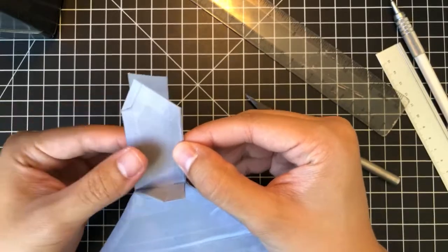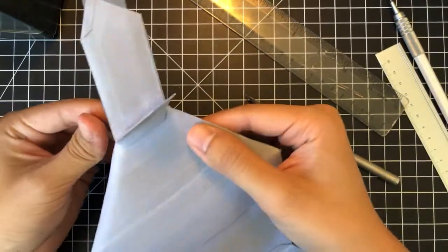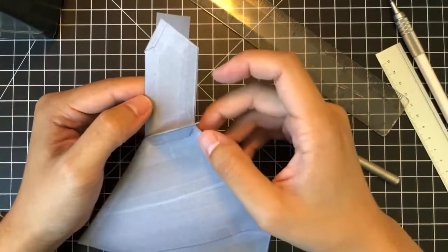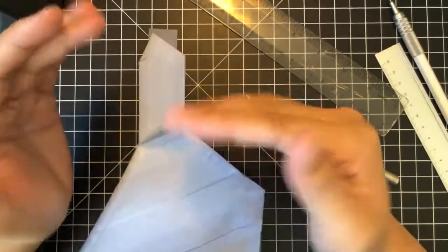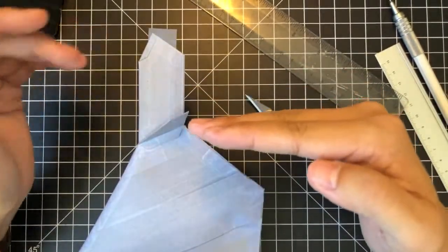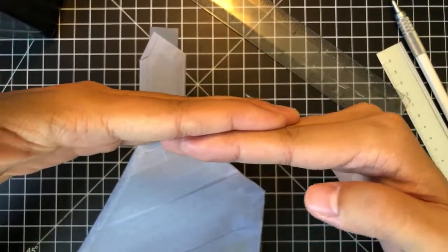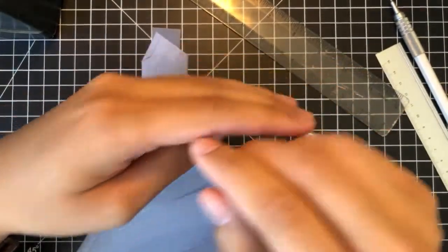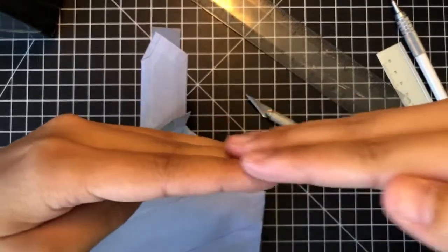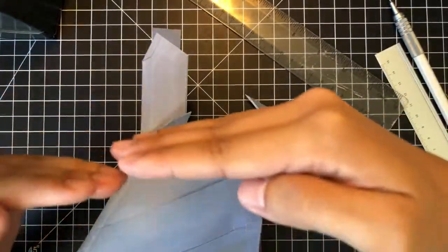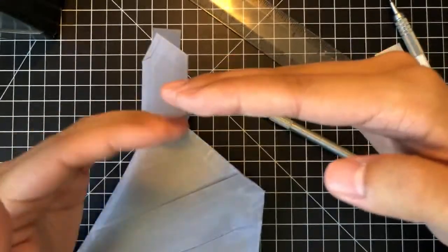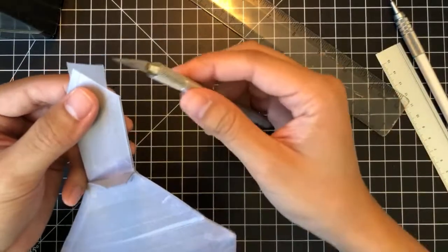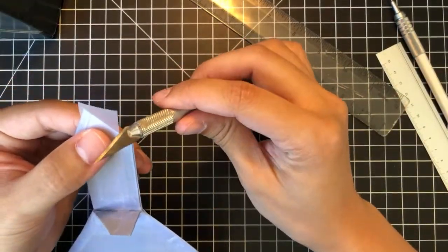Ideally, when you do this lamination step, you go from the trailing edge to the leading edge. And the reason for that is you have your tape layer in the back and you layer on top of it like this, and then you layer on top of that, right? And then curve over the leading edge. And so what that does is it creates the step going back instead of the step meeting the incoming airflow. So it's a tiny detail, but ideally it would be like that.